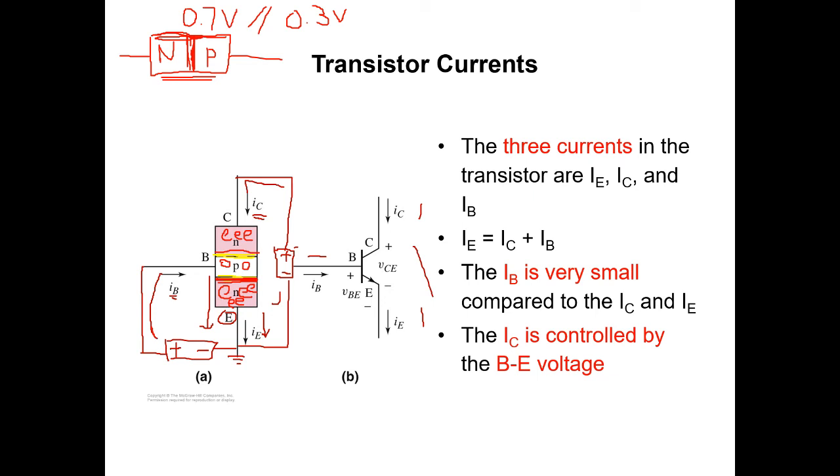So where is this region inside the NPN transistor? You can see there are two depletion regions over here and also over here. But do these two depletion regions have the same value? Here you have the emitter part, you have more carriers, right? More carriers compared to the collector part.